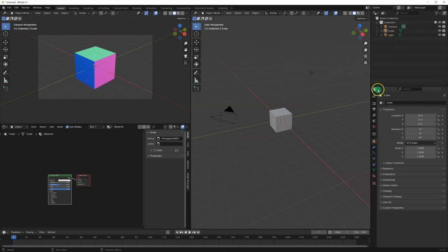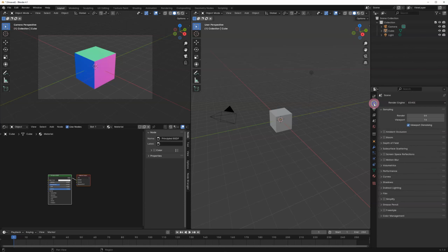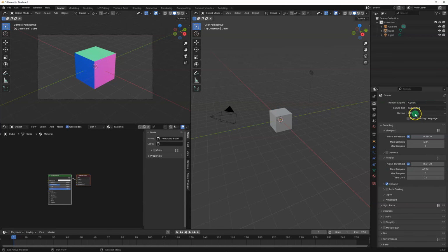and as we add more objects, more things will appear. Under the tool and under the rendering, we need to set the rendering engine not on Eevee. This is a real-time, like gaming engine rendering. We need to turn it to Cycles, and we need to turn the device from CPU to GPU. Here we can change the viewport samples. Instead of rendering 1024, we can make it 256. And here on the noise threshold, we could change it from 0.01. We could just change it to 0.1. And then here we can go divided by 4.